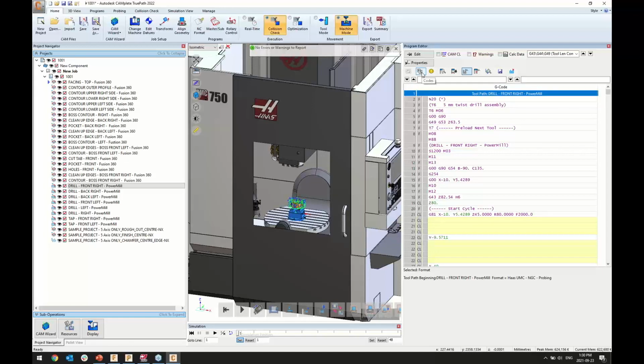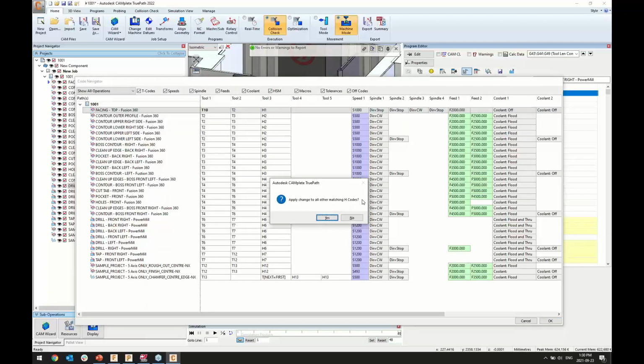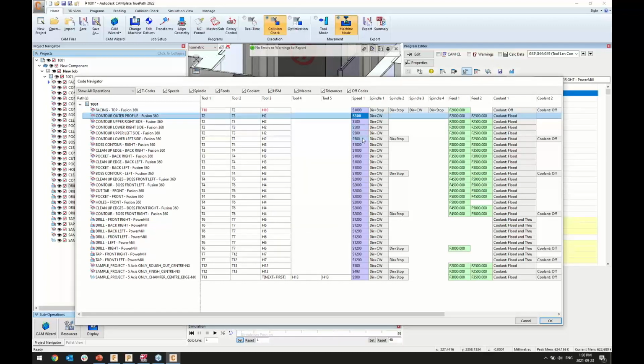So what we call the technology that goes around the toolpath is really an example of some of those points that I'm talking about. So the first thing we did, for example, was to change the tool number. So again, if we change the tool number, chances are the offset number will want to be matched as well. So again, being able to see those changes reflected right away.